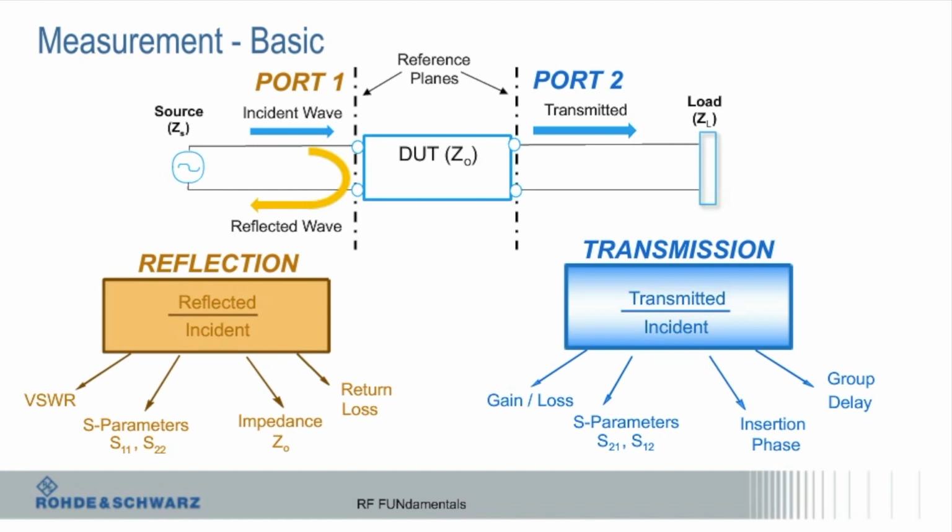But then you sometimes have cases where a signal goes in the wrong direction, right? Say I have a power amplifier and it's connected to an antenna. If somebody breaks the antenna, and you've seen that in the old car radios, I don't think they have whip antennas anymore on cars, so I'm dating myself again. Somebody would break your antenna, and maybe your car wouldn't work. But on the transmitter side, that's a much bigger deal because it could be a huge signal. If you remember the FM AM radios, it was like a kilowatt. If you put that kilowatt into an open where all that signal gets reflected, and it wasn't designed to handle it, it'll just vaporize everything.